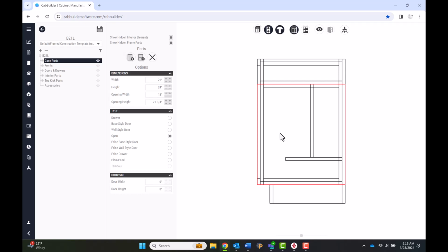This reveals that the front divisions really represent the boundaries assigned to the front part, rather than the actual door or drawer front. The front element's width and height are used with the applied reveal or overlay settings to get the actual door size. This is why there is a secondary set of dimensions called opening width and opening height. This is the same as width and height in frameless construction, but represents the frame-to-frame dimensions in framed cabinets. You may edit front elements by either method.